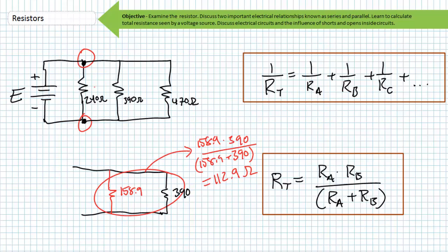Notice at no time did anyone's hands ever leave the single node at the top of our parallel relationship, nor did anyone's hands ever leave the single node at the bottom of our parallel relationship. Order doesn't matter when you're all hooked between the same 2 points in a parallel relationship. This simple fact can be used to your advantage in parallel arrangements with more than 2 resistors. Engage targets 2 at a time using the 2 resistor parallel formula in whatever sequence you wish. Take advantage of shortcuts, and not only will you get an answer quickly, it'll be correct.